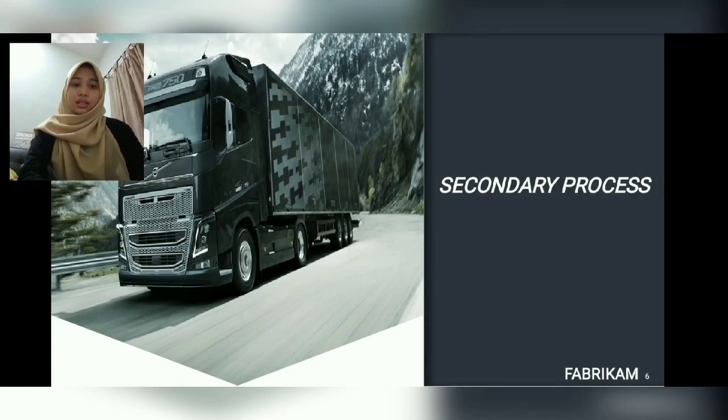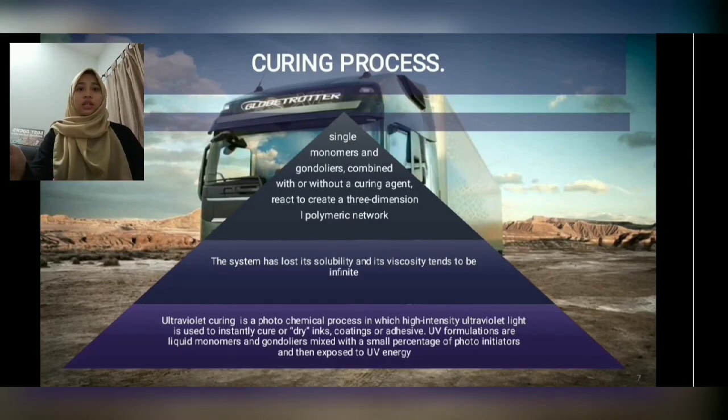Okay, next is the secondary process, which is the curing process. During the curing cycle, single monomers and oligomers combine, with or without a curing agent, and react to create a three-dimensional polymeric network. In the first part of the reaction, molecules with various structures are created and their molecular weight rises in time with the magnitude of the reaction until the size of the network is equivalent to the size of the product. The system has lost its solubility and its viscosity tends to infinity.